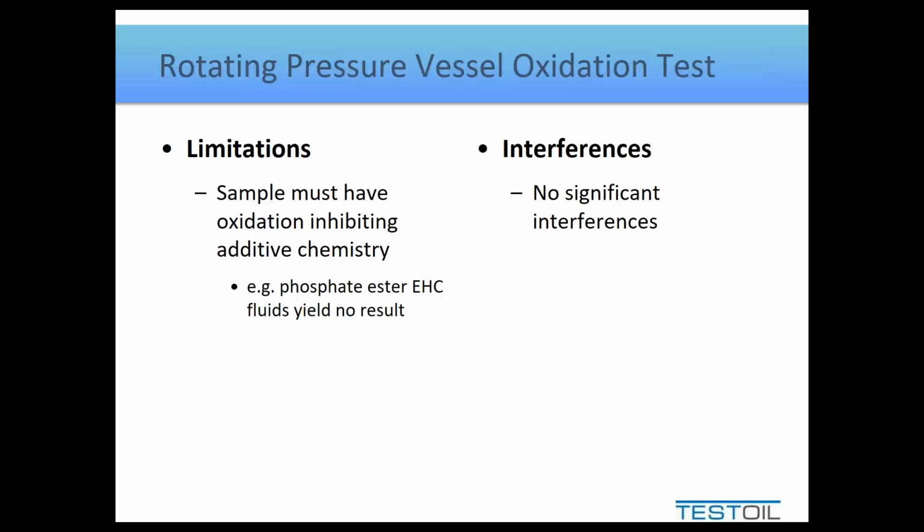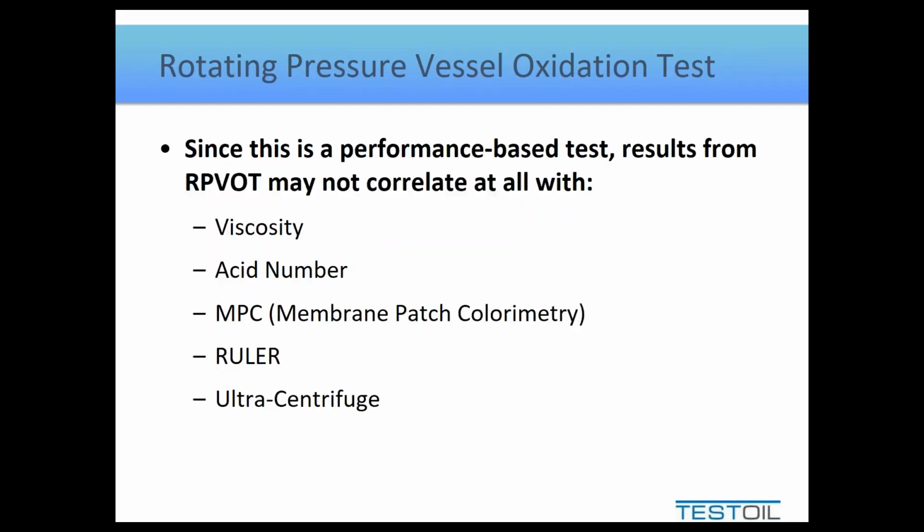Now, when it comes to looking at this oxidation test, most people are looking for confirmation that significant degradation is occurring or potentially will occur. So the common tests that we look for, surprisingly, actually don't correlate very well with this test. So remembering that this is a performance-based test, RPVOT will not necessarily correlate with viscosity, which is a physical property.